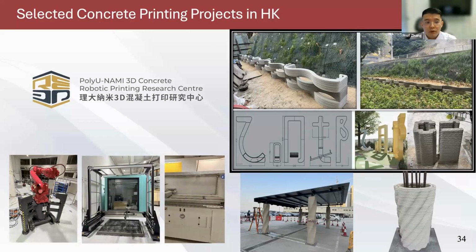It can print up to 4.75 meters high, and the printing range is 2.5, if I remember correctly. This is a gantry type printer. It has a slower printing speed, but it's more stable. The printing area is 2 by 2 by 2 meters. This is a powder bed printer. It can achieve more precise printing jobs.